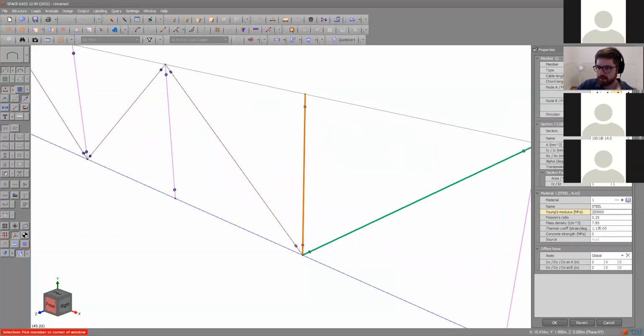If you're designing a web plate connection, which allows rotation and doesn't transfer moment, you need to use a pinned release, which allows rotation in the relevant axis, normally about the z-axis for 2D systems. If you're using a welded end connection or a flange plate end connection, which prevents moment, you need to make sure that's fully fixed. There's a whole course on this at 3340 because it is quite tricky.